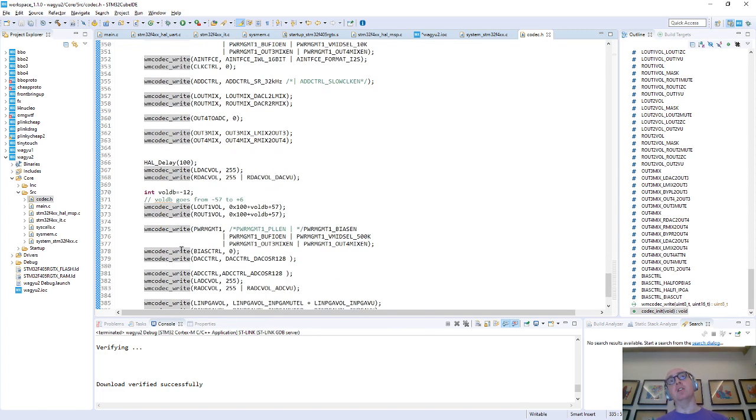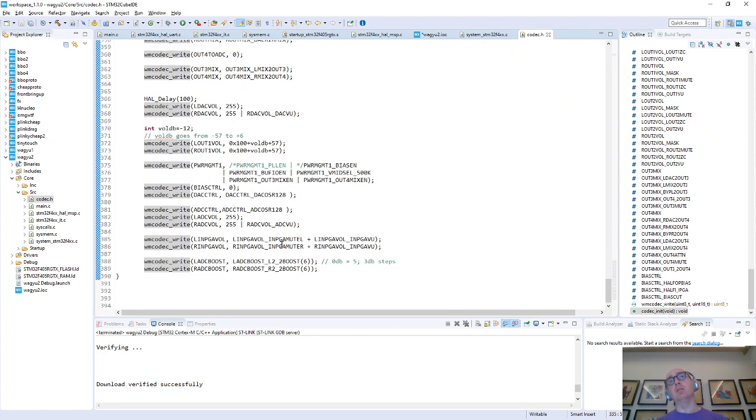So I need certain gains. I want certain bits of the chip to be on and off. And so you just do this. What's gross is if you don't get that right, and you don't get the HAL DMA stuff right, and you don't get the wiring right, and you don't get the PCB layout right, you'll just get a dead chip. So it was completely awesome that all the stars aligned, apart from my lack of pull-up resistors, and I was able to make the thing run.